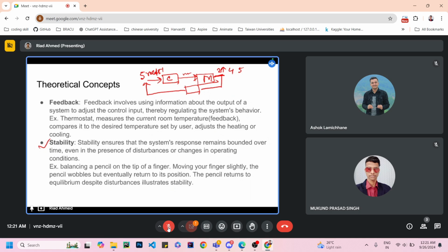You can't achieve 5 radian per second from the beginning. You have to spend some time to match the required value you have set. That is the amount of time required to make your system stable. What I'm trying to say is that when you have achieved this 5 radian per second value, that means you have matched your required value, right?